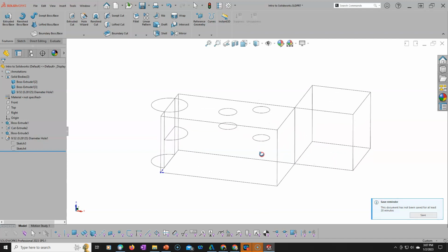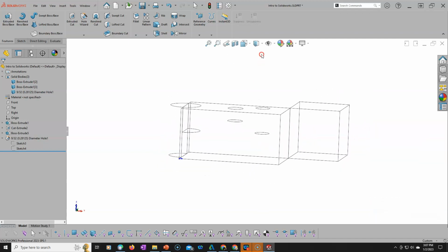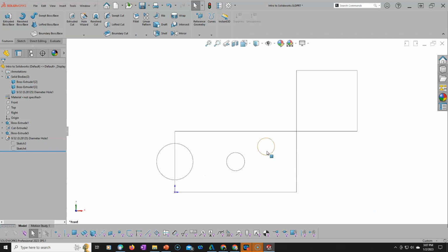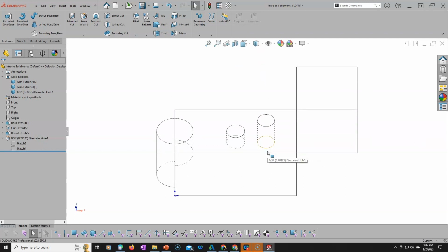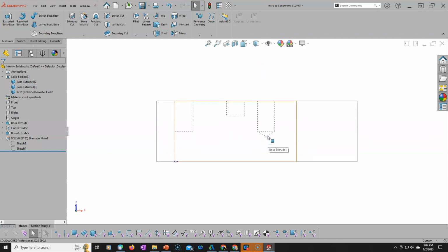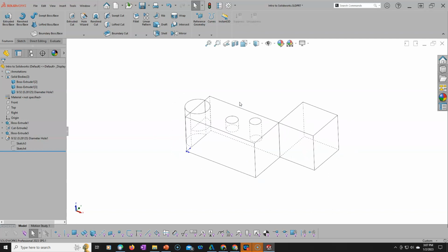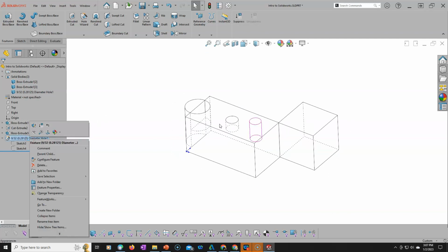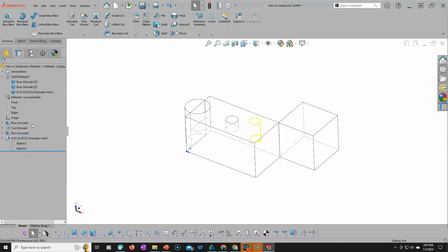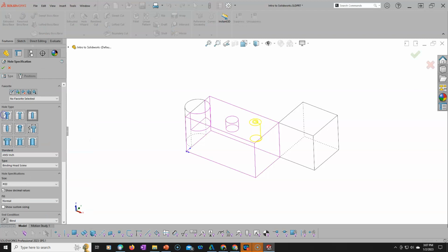There's different sizes for different applications. So if you do the 118 and the 135 is a little bit flatter, and my CAM software sees that shoulder, it's going to go depth, and it'll be a little bit deeper. So advantage here is this one I would have to create those counterbores. This one I decide that the Hole Wizard, I want to switch this over to a counterbore.